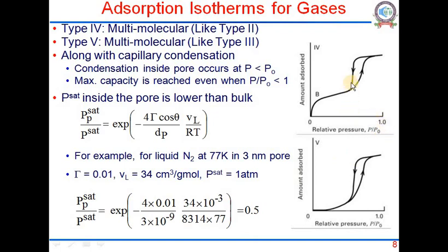So you can see that here condensation has occurred and suddenly the amount adsorbed increases because the liquid has gone inside the pore. A large mass of the substance goes inside the pore because it is present in the liquid form. So these are important when we try to adsorb and desorb the material, when we want to regenerate the material. So you need to trace the whole adsorption as well as the desorption curve to identify whether this kind of phenomena is happening or not happening.